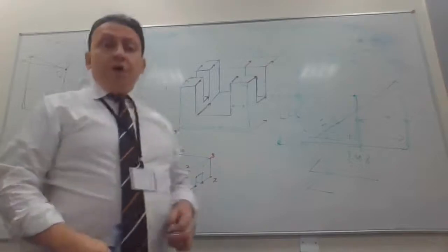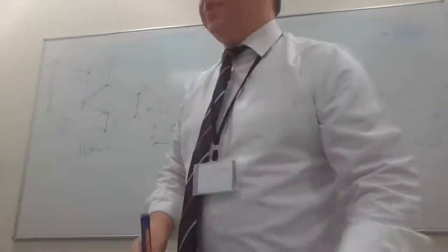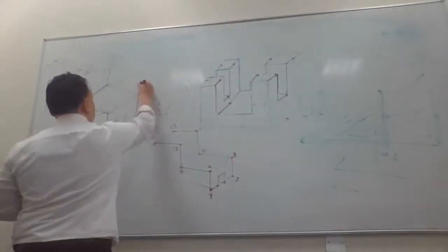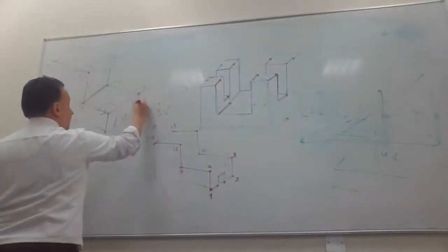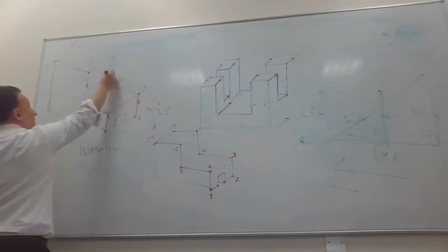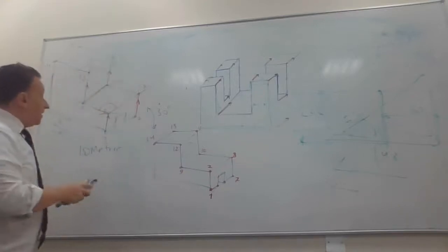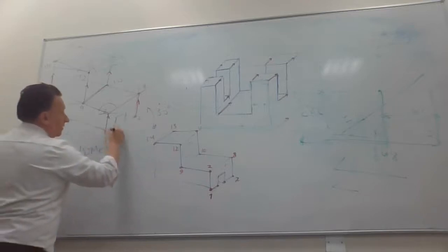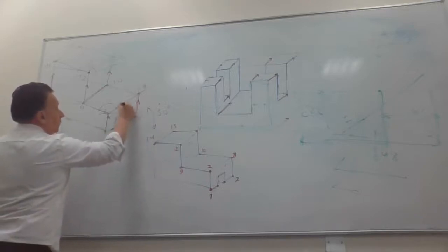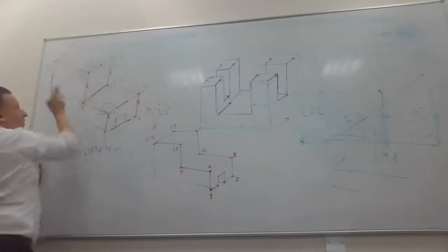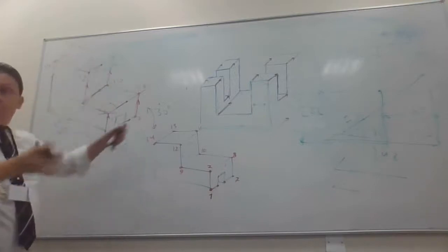And also, you have to maintain the parallelism. See, this line is vertical, so this line, this line, this line, they are parallel. These lines on this side, 30 degrees, are parallel with this one, this one, this one. They are all making 30 degrees to the right.